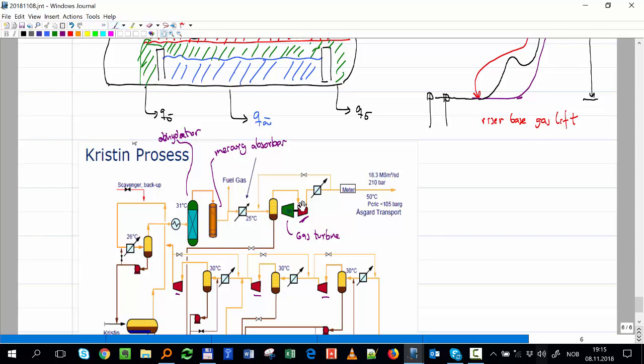The compressor has two driving ways, two main drivers. One of them is with an electrical motor. So you generate electricity in a generator and then you use it to move the compressor. And that's preferred. Or another way to drive the compressor is you put directly a turbine, instead of using a generator to produce electricity. But then you will have to use fuel every place you have a compressor, or you will have to have the compressor in the same place and the same axis connected to the same turbine.